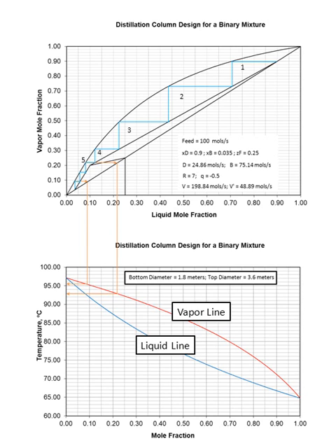Notice on the 5th stage we transition from the upper operating line over the feed stage, and then 7 stages would make up our column. This would include 6 actual trays, and the 7th stage would be our reboiler.